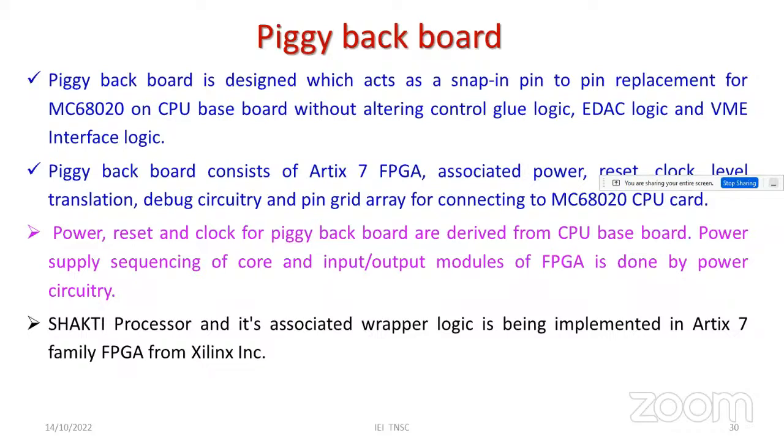This board consists of an Artix-7 FPGA along with power, reset, clock, level translation, debug circuitry, and pin grid for connecting to the 68020 CPU card.